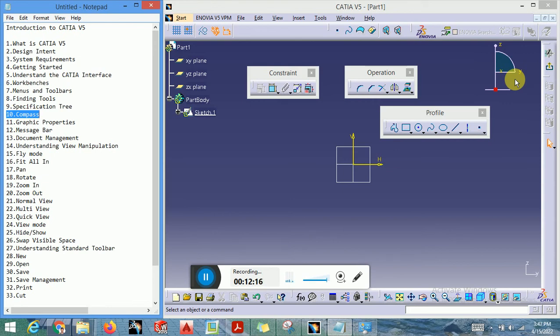In assembly we show exploded views for the assembly products. To create exploded views, we need to use the compass effectively to make the assembly drawing with balloons representing the exploded views. We will see in the Assembly workbench how to use the compass.